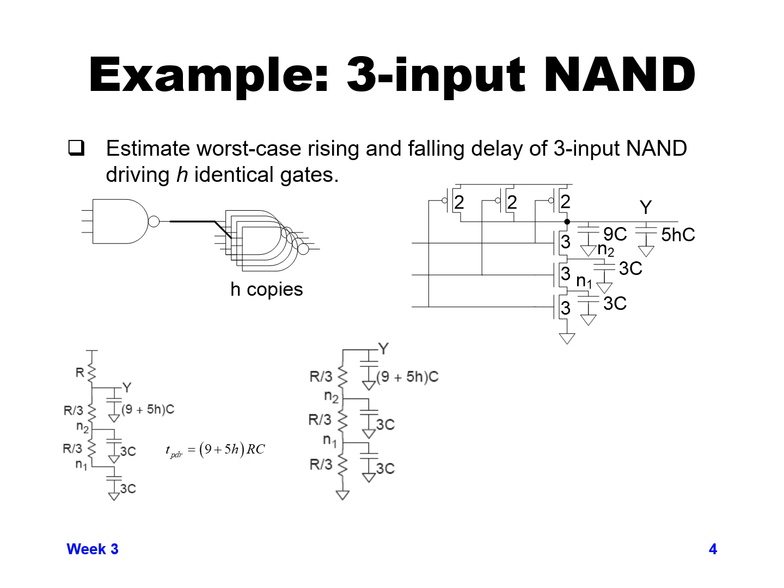As we were saying with the previous slide, the Elmore delay for an RC ladder comes out to be, for the first part that's closest to ground, a resistance of R over 3 that needs to drive a 3C value. So we have 3C times R over 3.